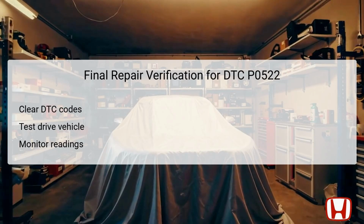Once repairs have been executed, it is imperative to clear the DTC codes from the vehicle system using the HDS. After clearing codes, conduct the test drive under various conditions to ensure the engine operates smoothly. During the test drive, keep monitoring the readings of the rocker arm oil pressure sensor closely. This final verification process enables you to confirm whether the repairs have successfully resolved the issue.